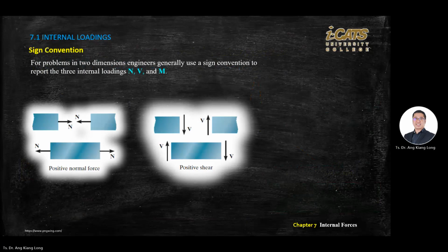If you have an opening, we always have anti-clockwise rotation, if you see it as a rotation. So on the left, always point down. On the right, always point up. By convention, it means if you want to solve any internal problem, you cut it. The visual one like this: the left hand component will point down, the right hand component will point up. No need to think. It's a way of doing things. Okay. Then if you cut the outside part, the left hand side always points up, the right hand side always points down.